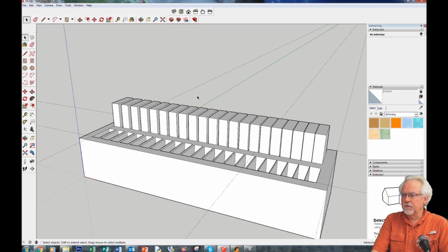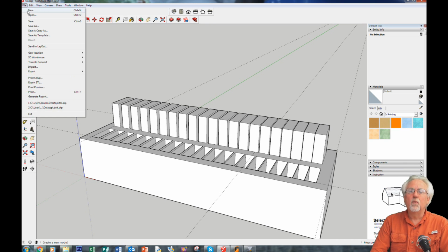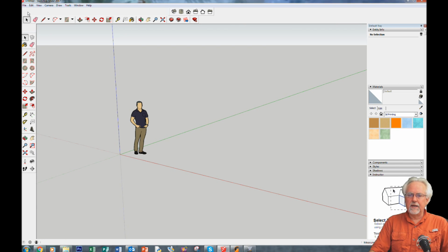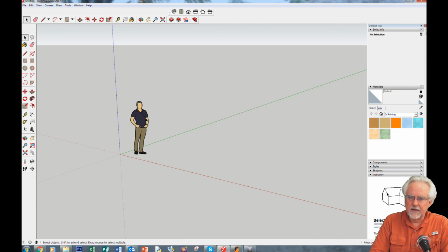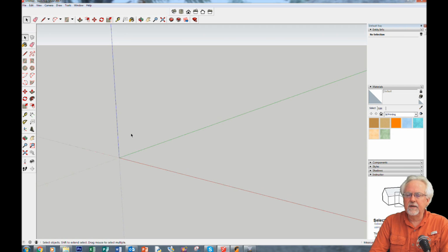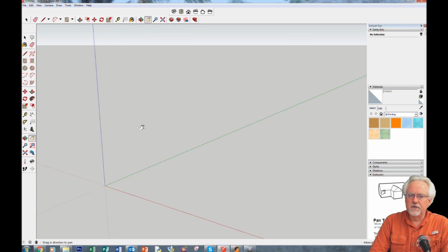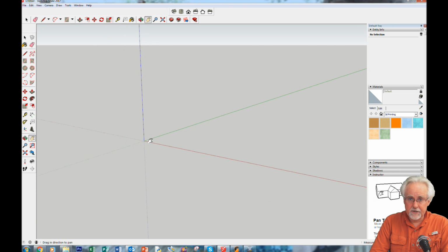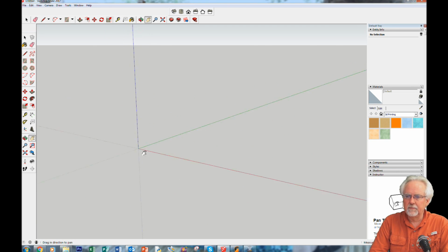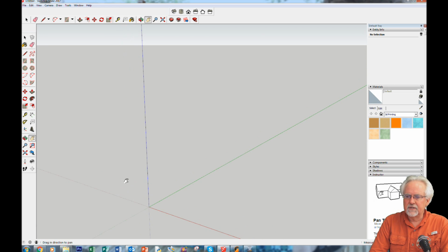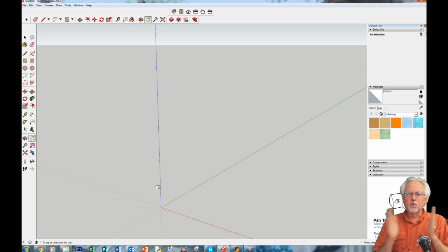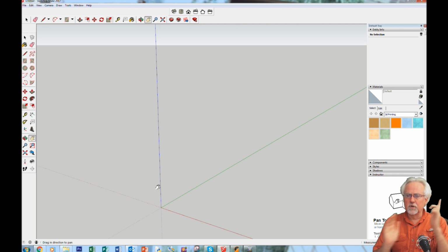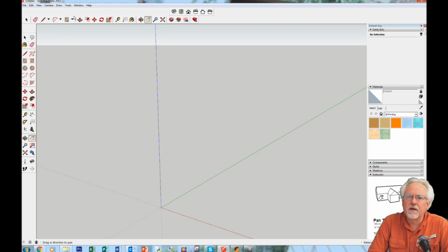I'm going to go through this and you're going to follow along with me and we're going to design this little thing. So we will start with a new blank sheet. We're always going to select this guy and delete him. We probably also need to zoom in because we're working in millimeters. Make sure that you open SketchUp to work in millimeters so we will be in the same units. And since we're working with greater precision, looking for our design rules, we have to make sure that our setup is very precise.